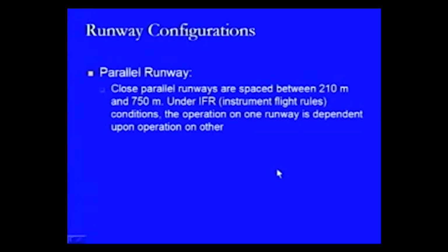Then in the case of close parallel runways, if they are spaced between 210 meters and 750 meters, under IFR condition the operations on one runway will become dependent upon the operation on the other runway. That is the problem in the case of close parallel runways.